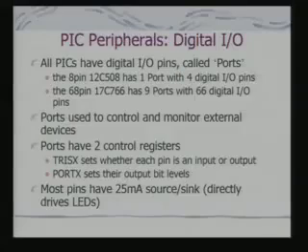So with this background on interrupts, we shall now look at the different peripherals, because many of the peripherals would be interfaced or can be interfaced using this interrupt processing structure of PIC. The most common peripheral is digital I/O. All PICs have digital I/O pins and we call them ports.